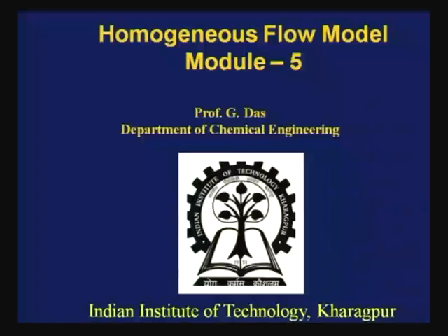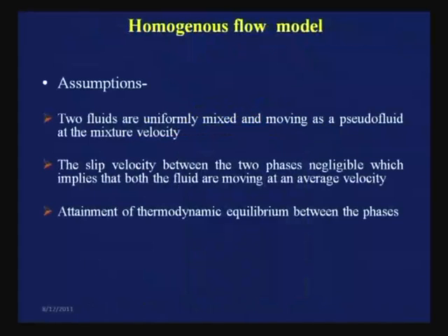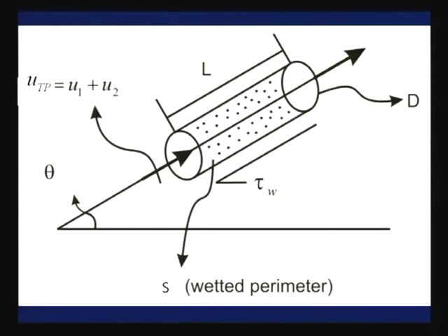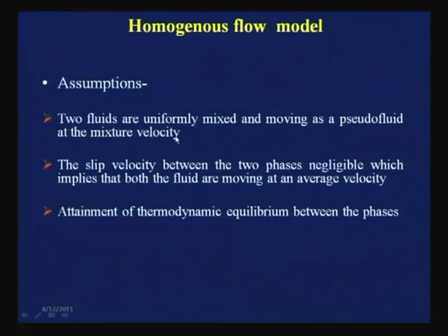So today we are going to start the homogeneous flow theory, the simplest possible analytical flow model which we are going to discuss. Here, what do we assume? We assume that the two phases are thoroughly mixed up with one another, completely mixed up, so that they can flow as a pseudo fluid.